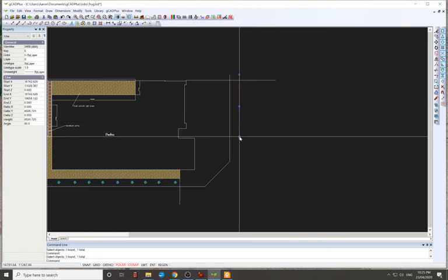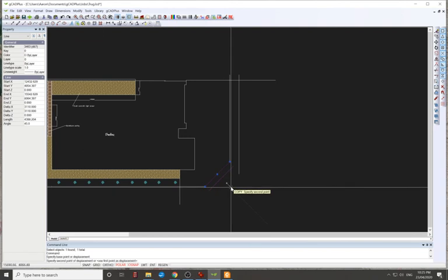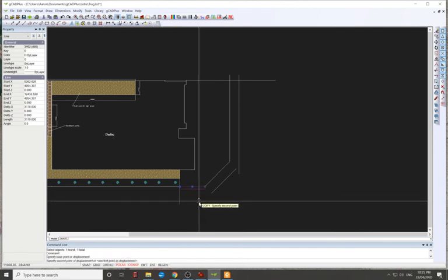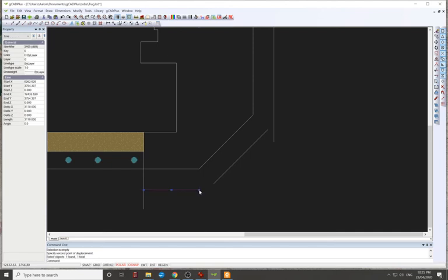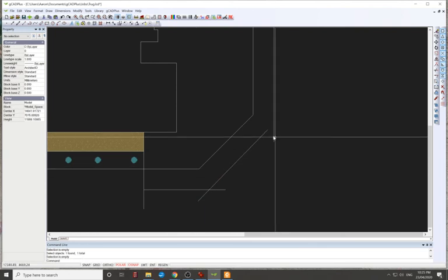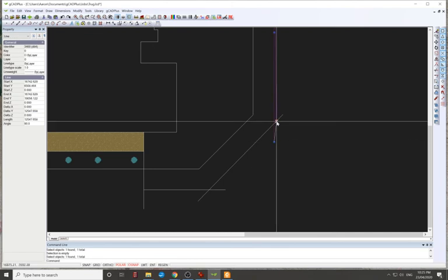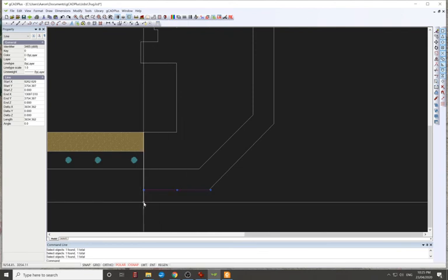This footpath we might just keep in there. We might replicate that. So copy, we'll put that out at 1200, and we might do the same on this one. Gives them some point of reference, and I'll just drag that a bit further that way. This one over that line again. Should stay there. I think it went off a little bit. Again, I could trim them, but I'm pretty happy just doing it that way. Trim this one too.